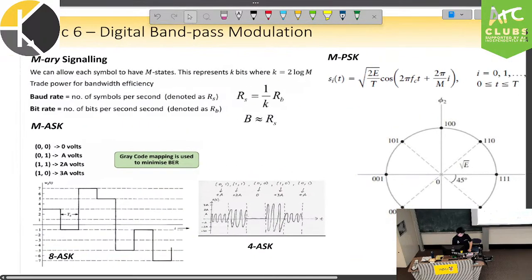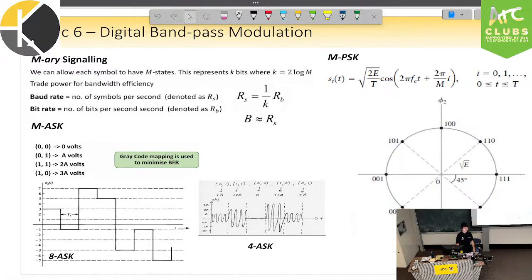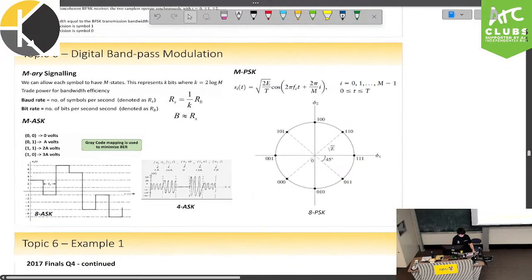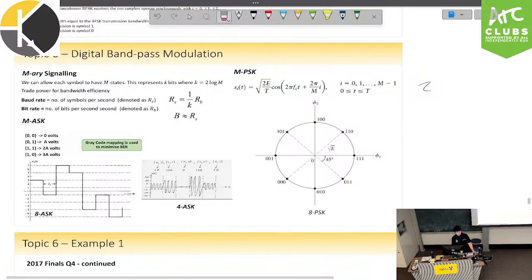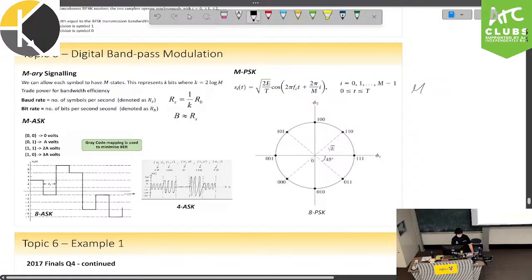So we have M-ary signaling. M just really stands for a number if we want to push past using just 2 levels in our binary. Something goofy, which I'm pretty sure they get wrong in the slides for the course, is they refer to M-ary as 2 to the M at some point, where it's very questionable when in all the cases they're just referring to M. M in this course is purely going to refer to the number of levels. So binary is 2-ary, which is a little bit silly, but yes. If I want to use 16 values, or in other words 4 bits, I have to use 16-ary. Good stuff. Let's keep on moving.